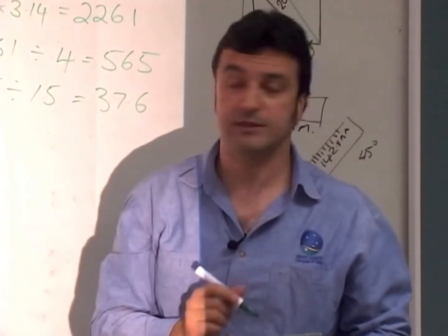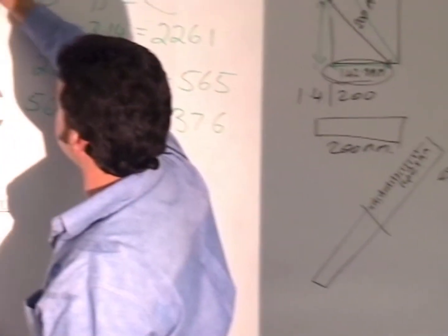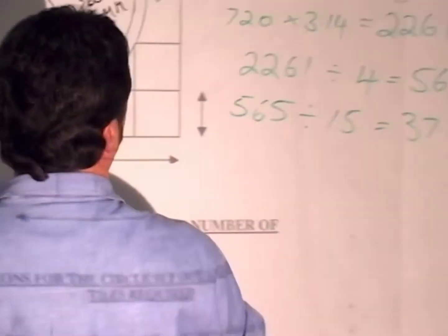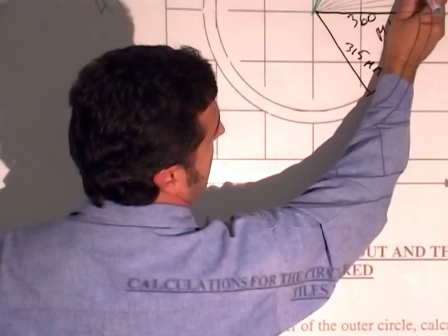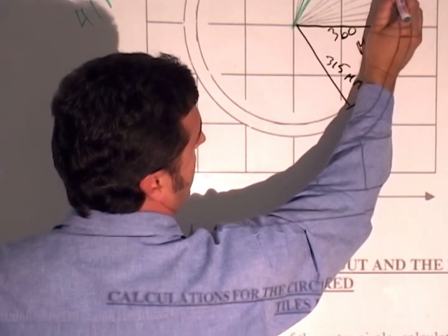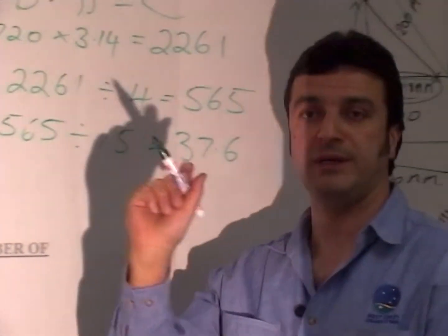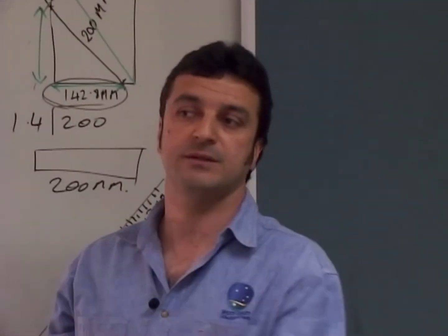And to answer your question, Mark, once we put our tile across in a strip that we've cut, we're simply going to reduce back 1 millimetre either side of the line, and the next piece will be cut back 1 millimetre off the line, and that'll give us the 2 millimetre space that we need. So our work will be consistent all the way through.